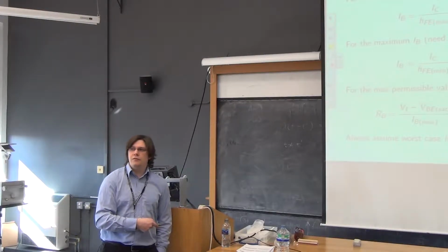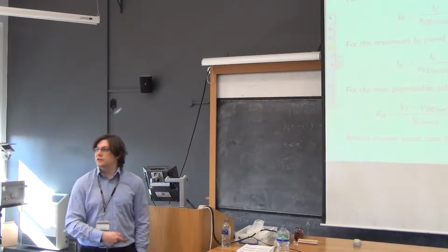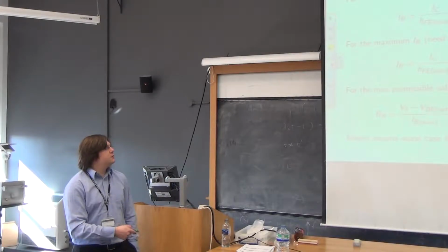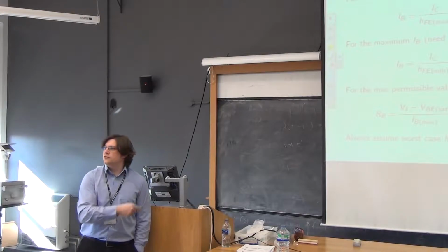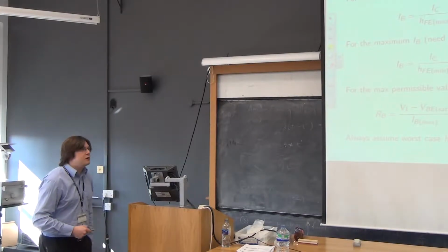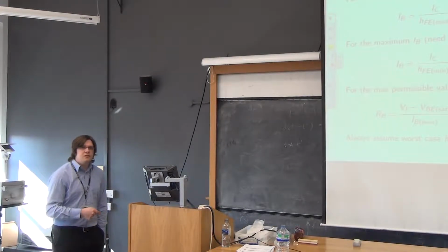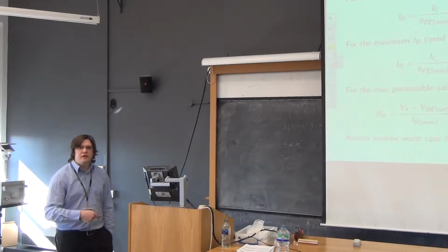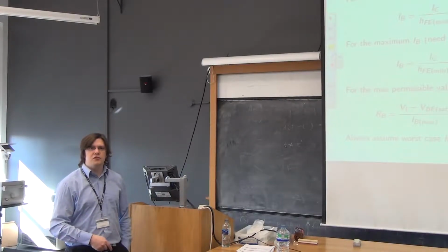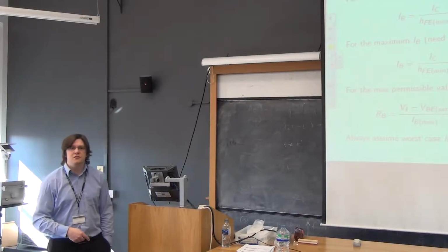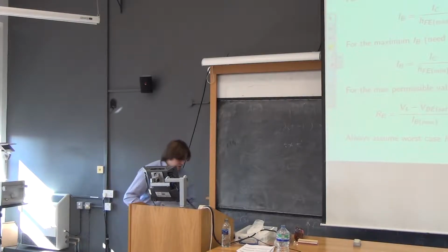And if you put that higher value resistor in your circuit and then try and run it and find it doesn't have the biggest HFE that you wanted, there will be too much voltage dropped across this bigger resistor to admit this current and still make the transistor switch on. And that's why it won't work. If you feel unhappy about that at the moment, have a go at a couple of questions, work it out the right way, and then work it out the way that you think it ought to go, and convince yourself the numbers don't add up, quite literally. And you'll be happy about it.